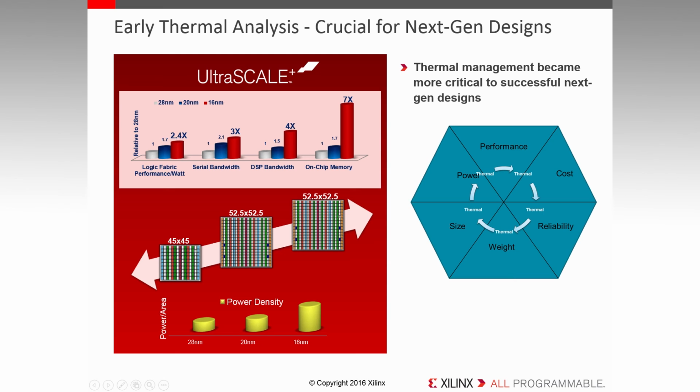The FPGA design and system reliability, as well as electrical functionality and performance, are determined by the operating temperature under which all logic functions. Die temperature must be controlled because it impacts the timing, leakage power, package design and lifetime of the device. Circuits run slower when they are hot and their lifetime reduces exponentially with increasing temperature. Furthermore, leakage power increases exponentially with temperature, which can cause a thermal runaway.